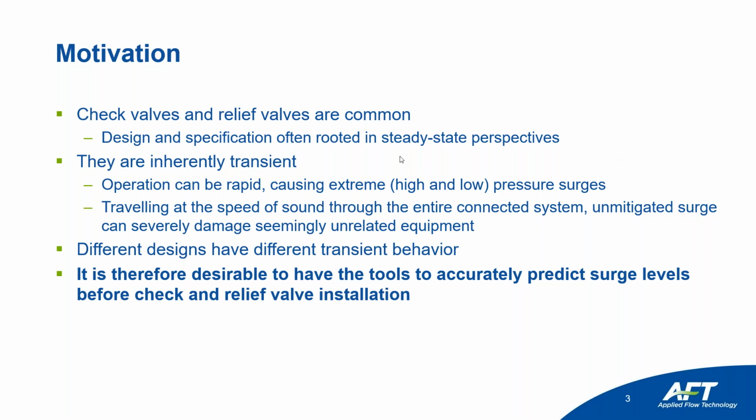Sorry about that. All right, so surge travels through the entire system at the speed of sound, and if it's unmitigated, that can cause really severe damage. And different designs of different check valves and relief valves have different transient behavior, so it's important to keep that in mind if this transient behavior is causing problems. And it's desirable, of course, to have some tools, AFT Impulse, to accurately predict surge levels before you actually go out and test these. We want to give you the tool to know if it will work, obviously.